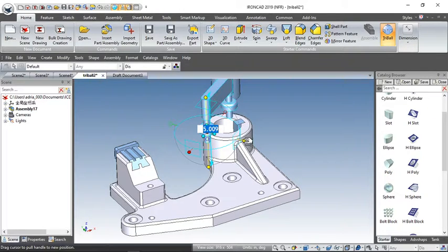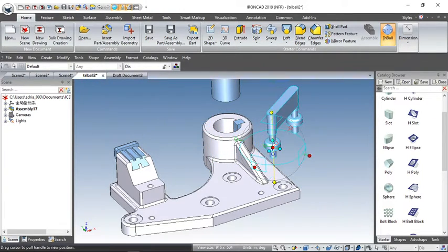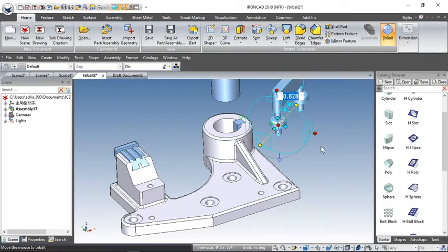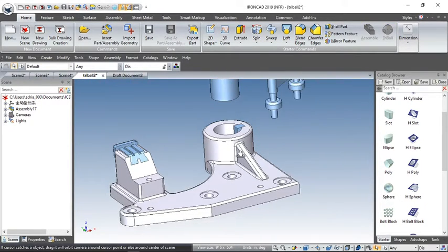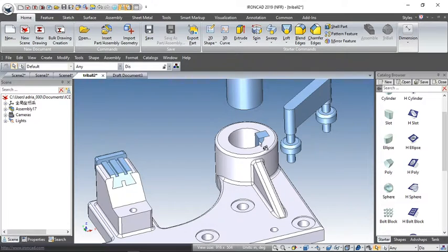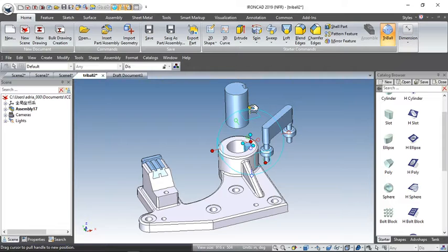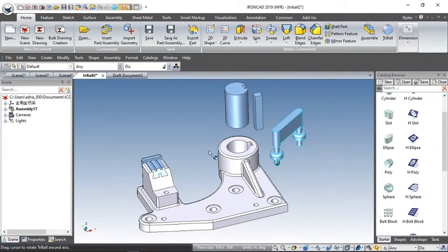Let's bring it over here, maybe move it up a bit. You can move these wherever you like. Press F10 to detach that one from there. And let's come into the keyway there. I'll press F10 again, and with the left mouse button I'm just going to bring that up there, and drag it back in here so that we can see it, and maybe just move it up a bit more like that. Let's bring it back a little bit, let's go that way. So there we've got our keyway like so, and maybe I'll come back in here and move that one out of the way so you can see all of that keyway.